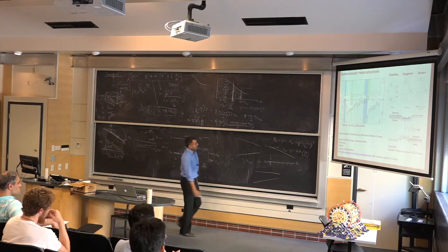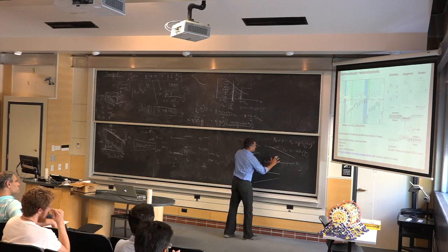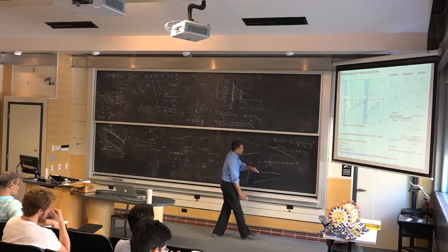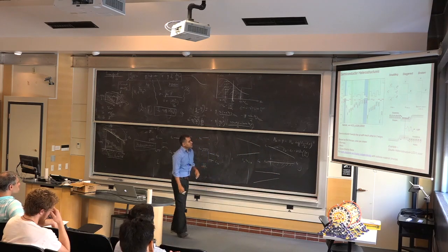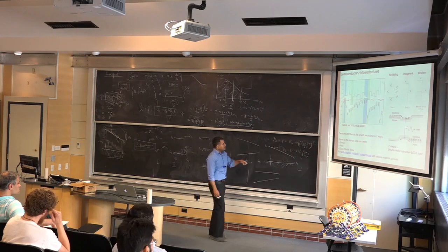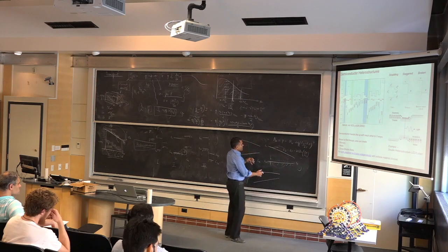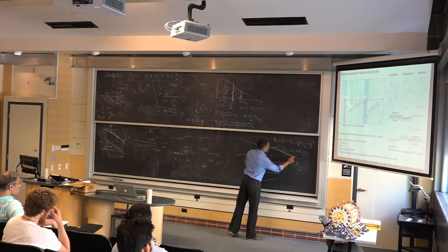This sort of behavior, this sort of structure, where you have silicon germanium graded junctions, is currently used in a lot of mobile devices, in a BiCMOS, where it's a bipolar transistor, but the base of the bipolar transistor is graded. It's a graded base. It's called a heterostructure bipolar transistor. Typically what happens, why do you grade it? What does it buy you?